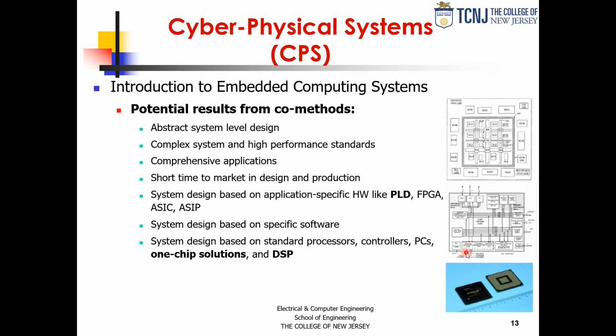So you actually want to make chips that are smaller, and now if I can put all these smaller chips together inside a single package, that gives me a lot of lower cost and more functionality integration. Because if I have a big die, it just takes one defect in this corner, and it's random, the whole die is bad now. But if I make the die smaller, the probability of that defect landing in my smaller die is smaller. So there is a higher probability of the die being good, just from intrinsic defects. There's nothing we can do about that. Those are anomalies in the lattice of the material.